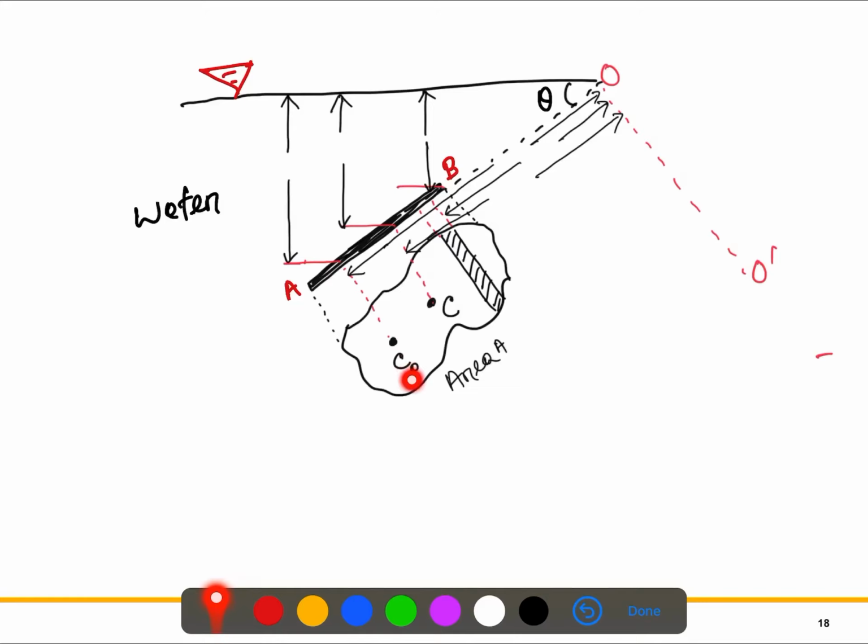When we have a plane surface, the hydrostatic forces form a system of parallel forces. So we need to determine the magnitude of the force and the point of application, where it is working. This point of application is called the center of pressure, and this is the centroid. Now, we'll not make this video long, but we'll try to make it short.